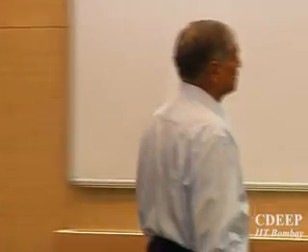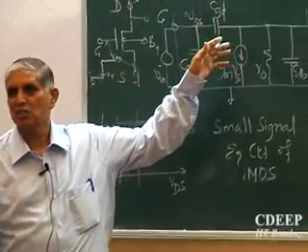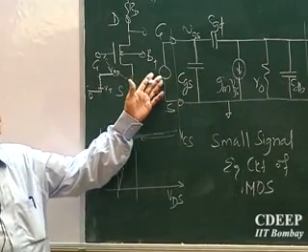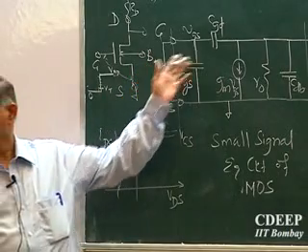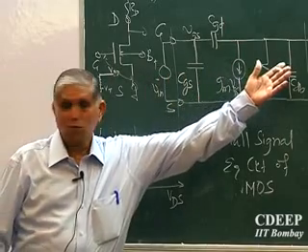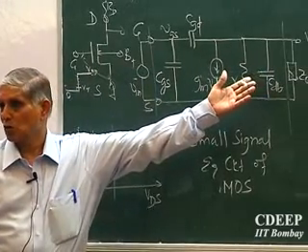Okay. In that case, VGS minus VT always will be smaller than VDS. Device will remain in saturation. And the current which it can flow at the maximum is given by that equation. So in all analog circuits, why did we look into analog? Because this is an equivalent circuit which I'll use for amplifiers, analog circuits. This will be a sinusoidal input and we'd like to see sinusoidal output. Is that correct? This is my signal and that will be my sinusoidal output I am going to look into.